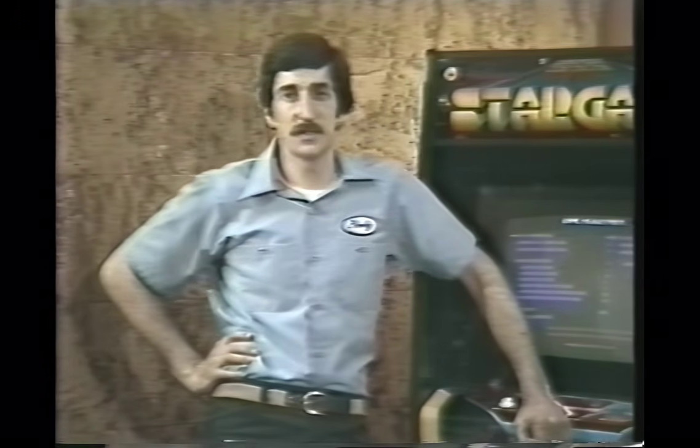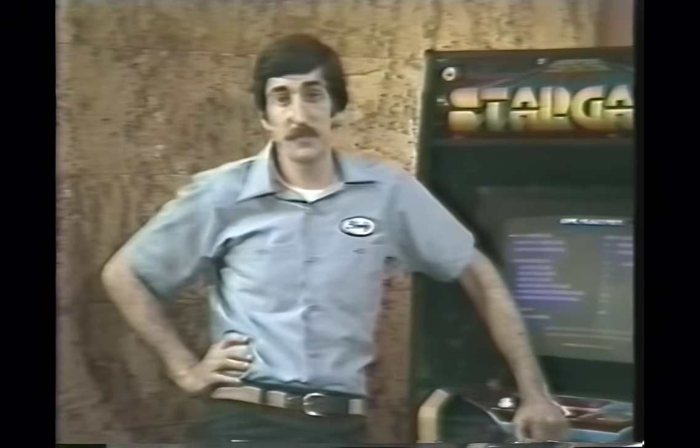For instance, say I had an 8,000 microfarad 16-volt capacitor fail. But I go to the store and all I can find is 4,700 microfarads at 16 volts. The voltage is okay, but the capacitance isn't anywhere near 8,000 microfarads. Well, if I get two of the 4,700 microfarad capacitors and connect the two in parallel, their capacitances will be added together. 2 times 4,700 is 9,400, so we're well above the 8,000 microfarad limit there.